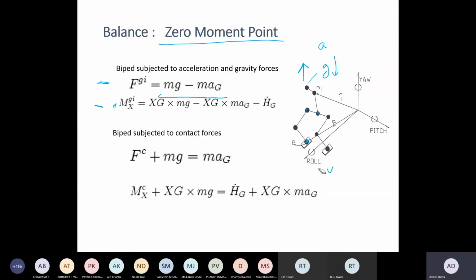Now, in terms of the forces, all the forces because of the lump masses will have a resultant in that direction at the ankle. It need not be at the ankle point, it can be somewhere else, but it has to be on the foot. And by Newton's third law, there will be an equal and opposite reaction which will balance it. So the forces do not cause any disbalance, the forces are balanced. But what causes a disbalance is the moments. There is a force acting like this, and a resultant force here. So this force into this distance has to counteract whatever moment is coming in that direction.